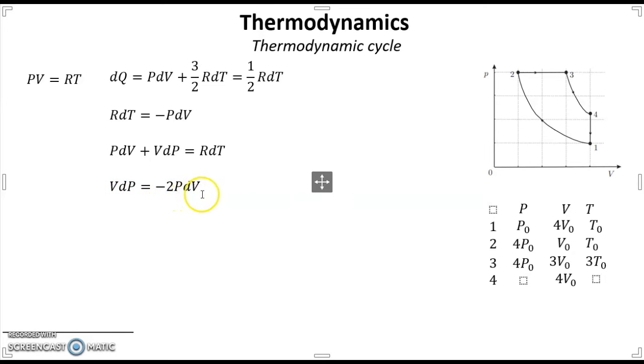This is how to express the dependency of volume and pressure during this particular polytropic process. Now we have to separate our variables. It has this form. And now we can integrate this process from point 3 to point 4. We have this expression. We have PV squared, it's a constant. And now from the universal gas law we can express PV as RT and insert it here.